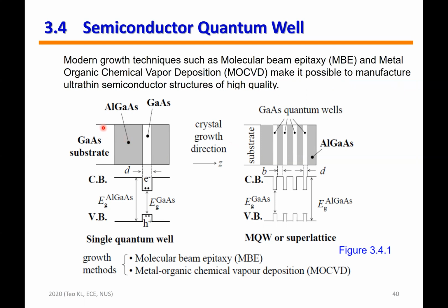The reason for growing another layer of gallium arsenide in the ultra high vacuum chamber is basically to smooth out any lumps or bumps of the substrate, because when you buy this substrate from the manufacturer it is mechanically polished and the surface may still have some lumps and bumps. So you want to deposit another layer the same as the substrate, which is gallium arsenide, to make an atomically smooth top surface before you grow the active parts of the multilayer.